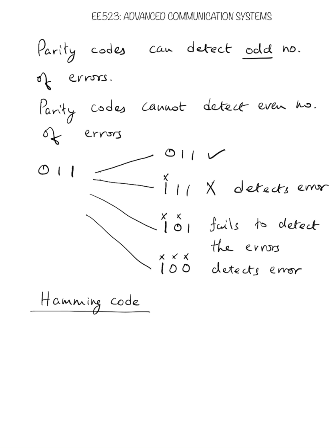Hamming codes can be designed with various code rates, but in this particular case we are going to talk about the 7/4 Hamming code. That means n is 7, the block length is 7, and the number of information bits is 4. We are going to have 4 information bits, and to them we are going to add 3 parity bits, so the total code word length becomes 7.